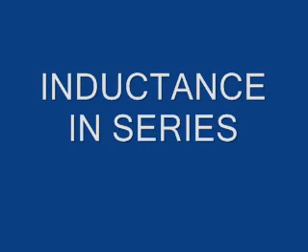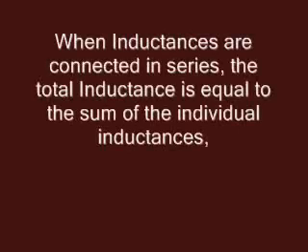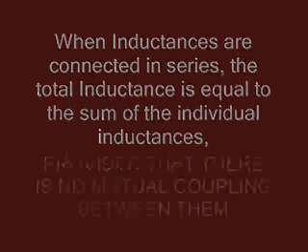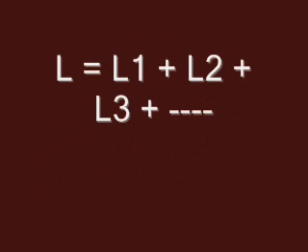Inductance in series. When inductances are connected in series, the total inductance is equal to the sum of the individual inductances, provided there is no mutual coupling between them. L is equal to L1 plus L2 plus L3, etc.